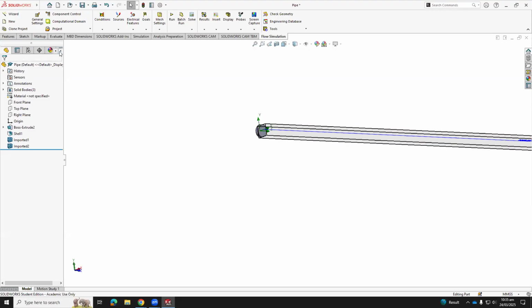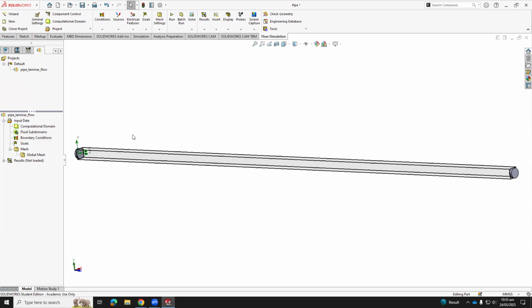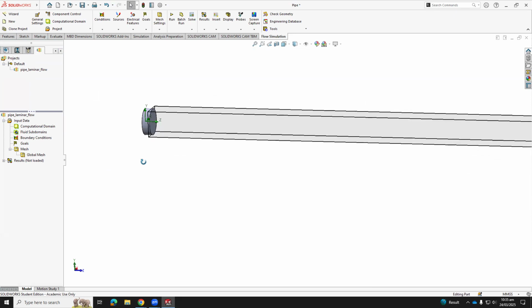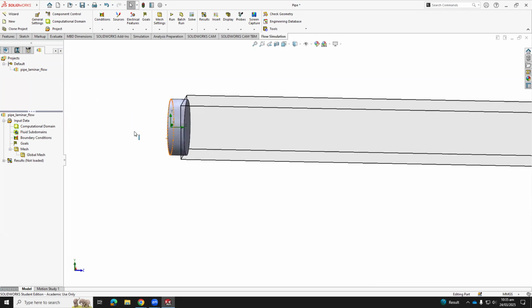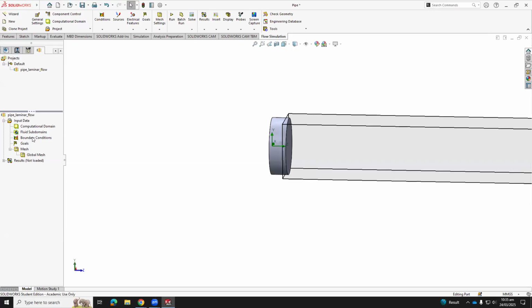Okay, I go back, arrows, see the arrow where I'm going to search for my computational domain. That's the nice way to move between the geometry and the things. By the way, you can do this in the tree. There are multiple ways, but I'm showing you the simple, easy way. Why do I need that? Because based on that, I need to ensure my computational domain, when I select my boundary condition, that face is actually covered with that cube. So I'll come first. Fluid boundary condition.